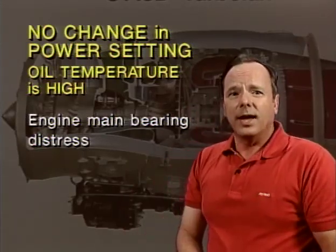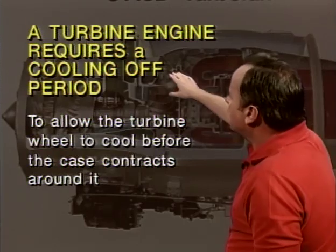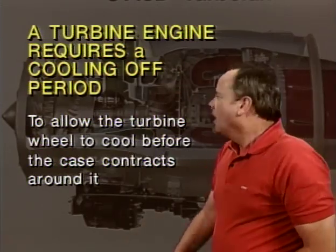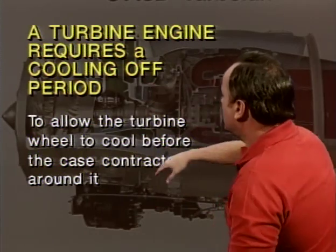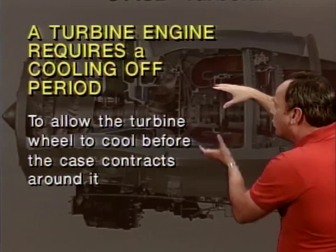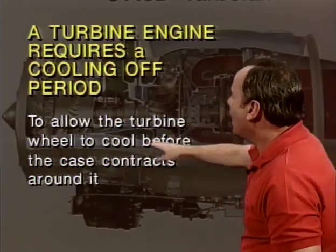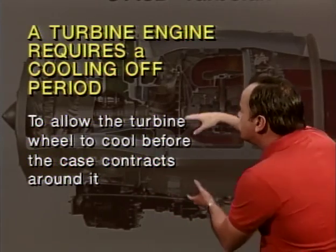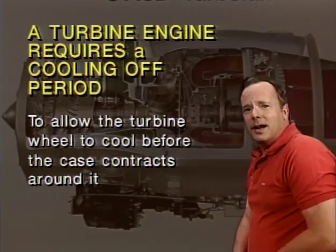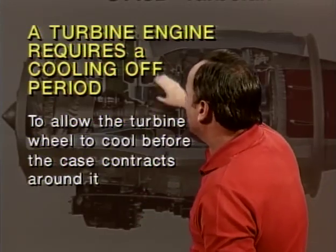Now, let's assume you've just finished a flight or running an engine very hard. One of the things you want to do is make sure that you allow, in some turbine engines, a cooling off period, because you want the turbine case to shrink at the same rate that the turbine wheel shrinks. Otherwise, if you do not allow the turbine wheel to cool, the case can contract around it, and that is a bad thing. And so, therefore, you should allow a turbine engine cool off period after operating at reasonably high power settings.